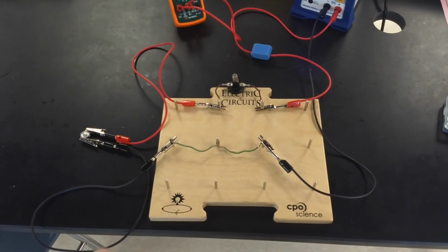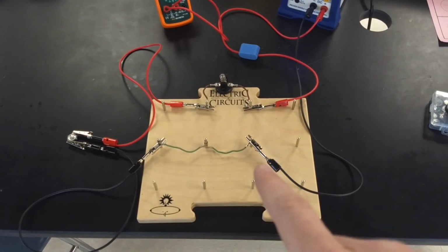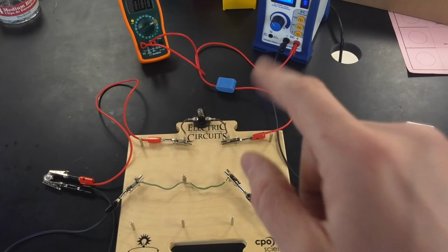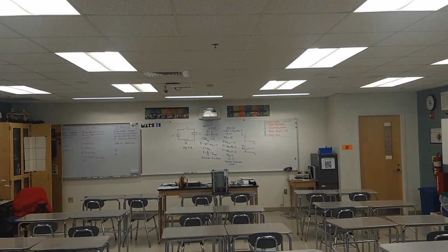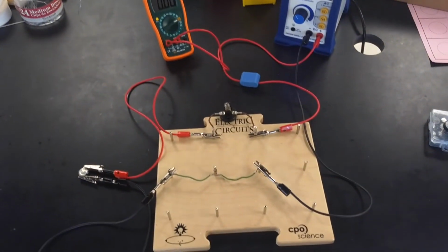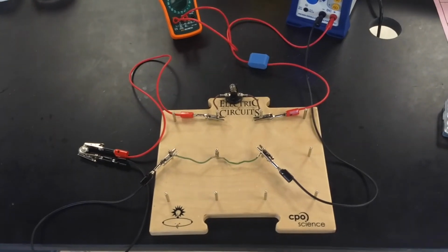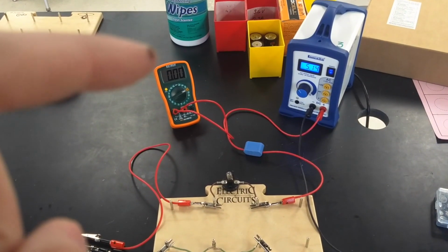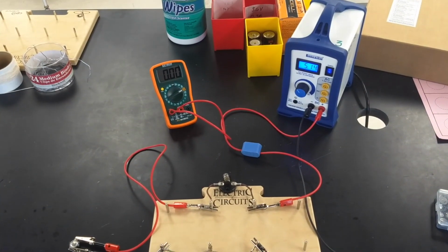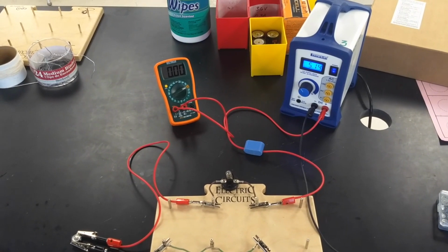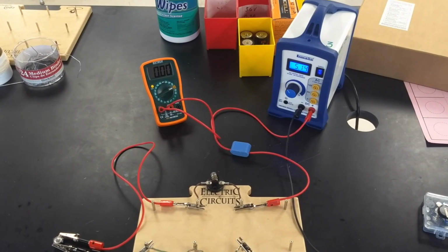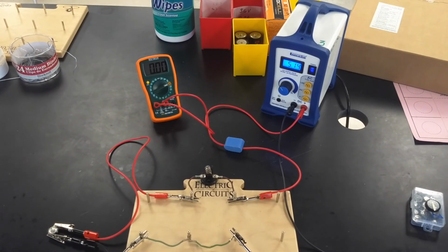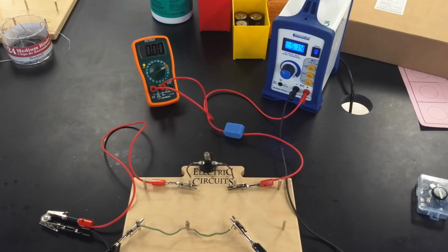So we have that, finally, the circuit is connected through this black wire back to the power supply. So what I'm going to do is, if I throw that switch, according to our learning on the board over there, then what we should see is that the current starts off at a maximum value and then slowly decays down to basically 0, but it should take a really long time because it's exponential, and exponentials actually take forever, so it's not technically ever 0, but small enough we can't measure it.